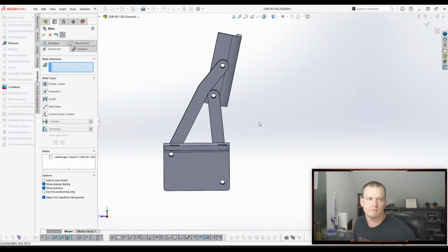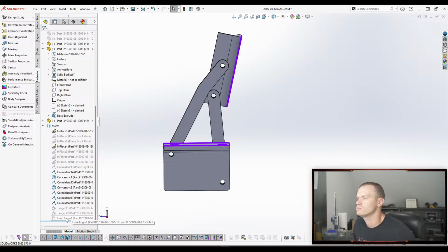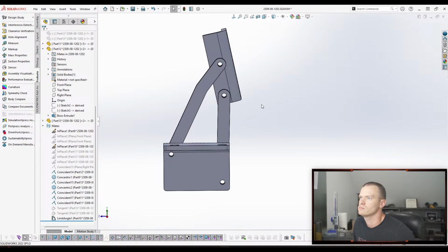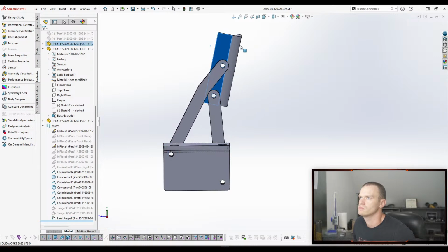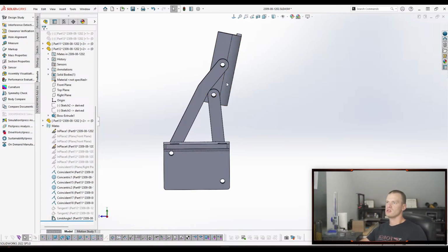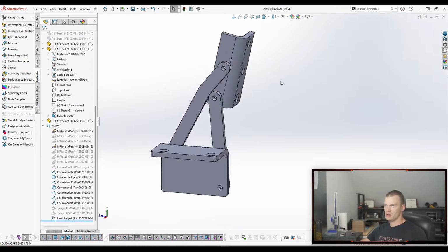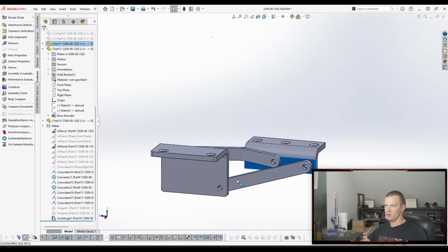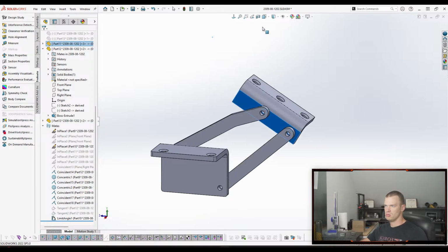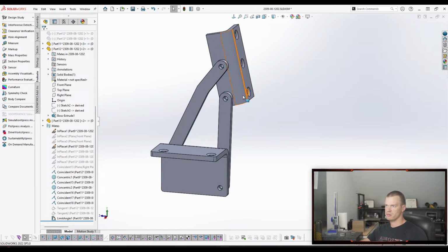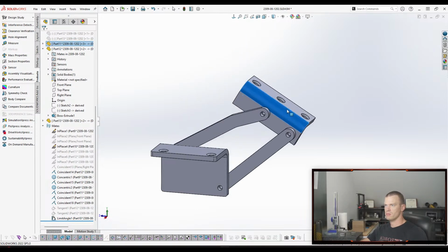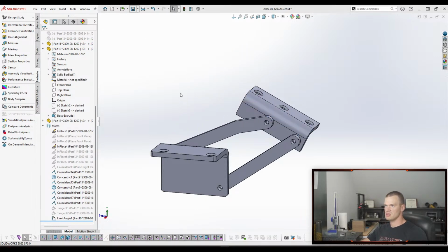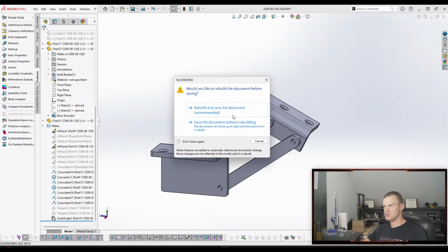Let's try that. Yeah, there we go. All right, so it was 102. So it was 78, but the other side of the angle. So now we have a mechanical mate that will control it from 0 to the 102 degrees open position, which is awesome. And the cool part is, just as a demonstration, we'll save this again so we don't crash.